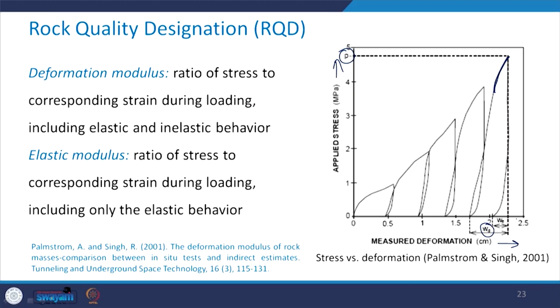So, the difference between deformation modulus and the elastic modulus is that in case of the deformation modulus, you have to consider elastic as well as inelastic behavior during the loading cycle. But in case of the elastic modulus, you consider only the elastic behavior. So, this is what I wanted to discuss with you today.